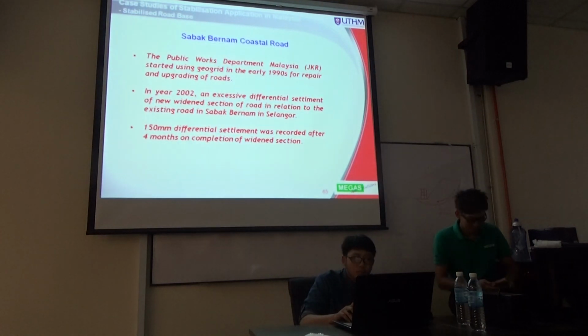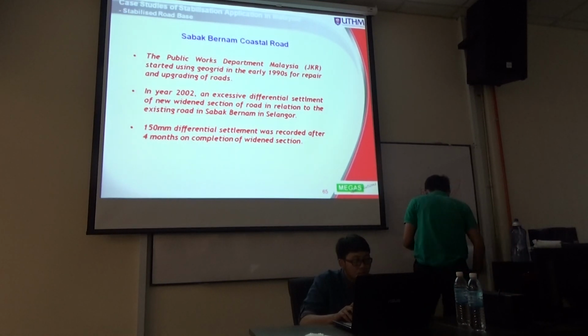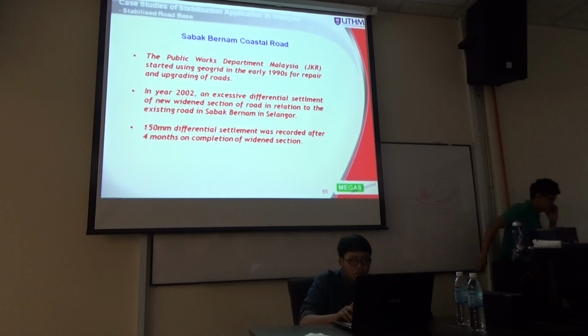Another one which I want to share with you is Sabak Bernam. Remember, just now I talked to you about differential settlement. So how can this tackle differential settlement? In year 2002, there was an excessive differential settlement on the new widened section of the road in relation to the existing road in Sabak Bernam, Selangor. It recorded about 150 mm differential settlement after 4 months on the completion of the widened section.